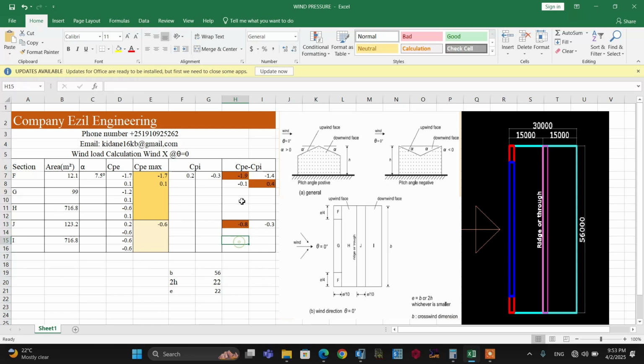So using all this data, let's apply all these loads to our project. Let's proceed to assign all these net pressure coefficients to our project, that is a suction load of 1.9 and pressure of 0.4 to this area, that is to the wind direction, and at the back, or at the suction zone, a suction pressure coefficient of minus 0.8.